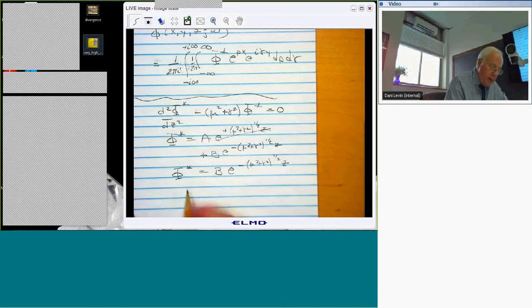The boundary condition, remember, was d phi dz at z equals 0 equals a combination of terms which I called W sub A. But now I'm going to assume simple harmonic motion, which will give me bars on both sides. I'm going to take a Laplace transform with respect to x and a Fourier transform with respect to y for this equation too.